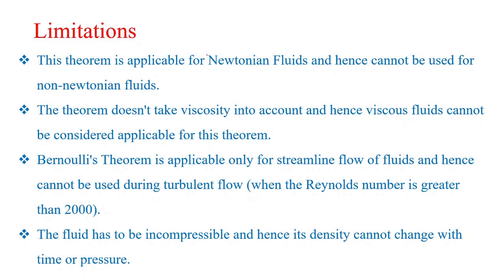This theorem is applicable for Newtonian fluids and hence cannot be used for non-Newtonian fluids. I already discussed with you what Newtonian fluids are. And this theorem doesn't take viscosity into account, so viscous fluid cannot be considered applicable for this theorem. Bernoulli's theorem is applicable only for streamline flow, hence cannot be used during turbulent flow, when the Reynolds number is greater than 2000. The fluid has to be incompressible.